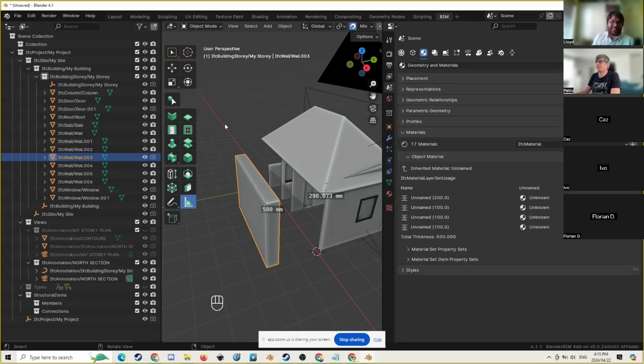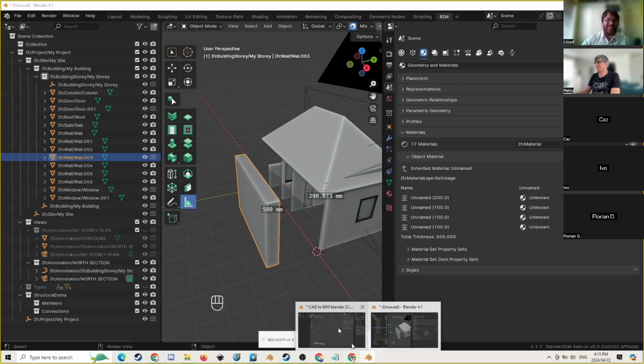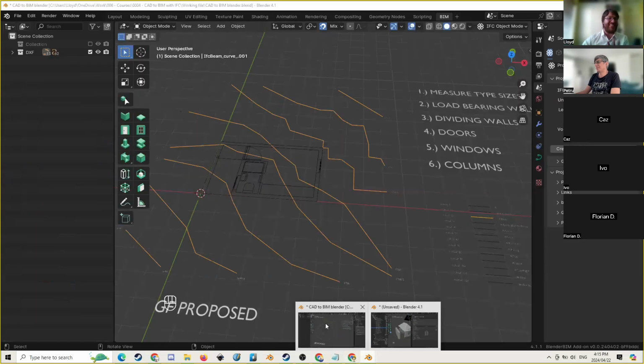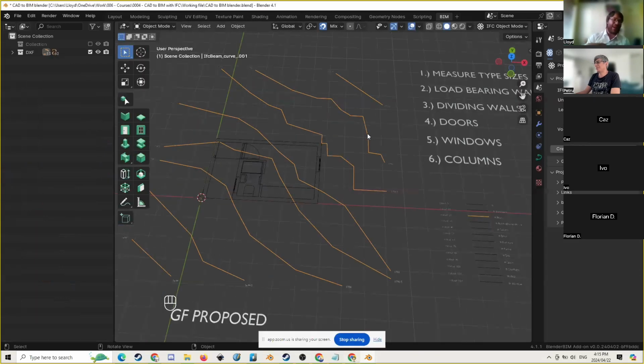I mean, this is a problem with anything that has links. It's not exactly clear. The process for Blender BIM changes all the time. So, especially if you have a link and you move a file because of an update or something along those lines, you're probably going to lose the link and then you're going to break your IFC or lose that reference. So that's why I prefer just saving the DXF in its own Blender file. But again, this is just my personal preference.